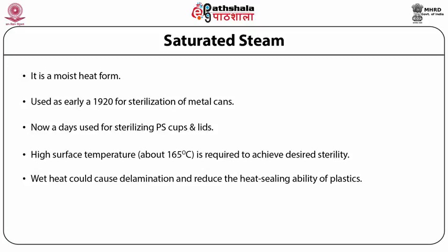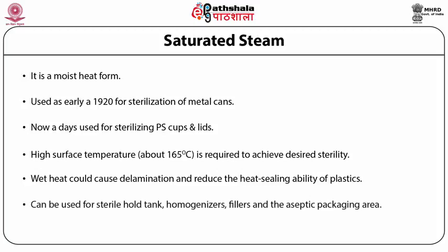Saturated steam is a preferred treatment method for sterilizing metal food contact surfaces downstream from the hold tube, including the sterile hold tank, homogenizer, fillers, and the aseptic packaging area. Equipment sterilization can be attained by exposure of the surface to an appropriate time-temperature combination. Example: 30 minutes at a surface temperature of at least 121 degrees Celsius by superheated water, saturated steam, superheated steam,